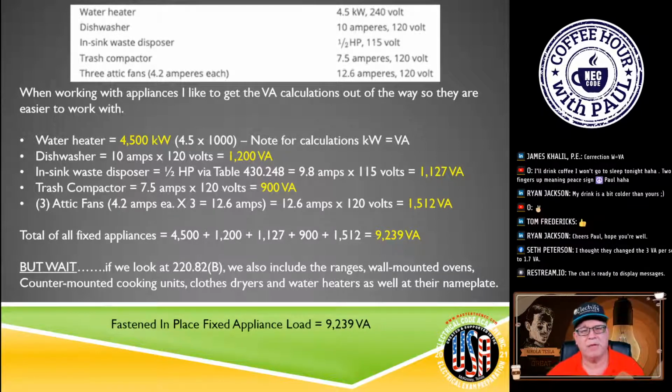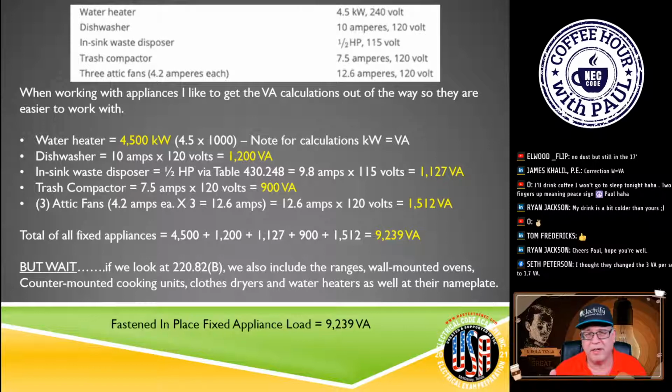All right. Now, so we've got that value. So we do 9.8 amps times 115 volts. And here's the thing. Always use the value they give you. If you're preparing for an exam, you and I both are sitting there going, well, you know, daggone well that 120 is the nominal. But if they give you 115, you're going to use 115. Of course, also with motor ratings, it typically corresponds with the motor rating, right? So it's 115 volts.